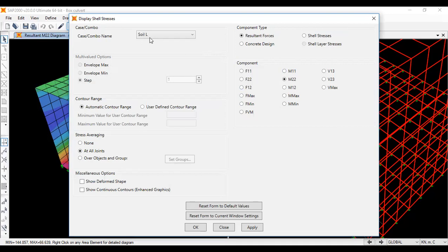So if you have the combinations, you can check the envelope max and envelope min, which will give you the maximum and the minimum. So if you need the maximums, you take the maximum from the envelope max, right? Let's say you have 6 surfaces, and that will give you the expected maximum of the 6 surfaces. That can even be a negative value as well, because there can be some surface where only negative values will occur, right? Among that, it will give the lowest negative, so that means the maximum value, right? So if you need the absolute, the minimum value, you need to check the envelope minimum, right? From that you take the minimum values, right? So this will only be open for the combinations, once the combinations are correctly modeled. Until that you can't do it.